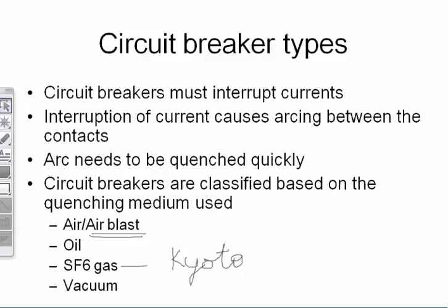It is a greenhouse gas, alright? It is a greenhouse gas, much worse than carbon dioxide. It depletes the ozone layer, much worse, alright? So you can use it. Yes, it depends on the government. Well, your options are somewhat limited for higher voltages. If you want really compact switchgear suited for higher voltages, you need to use SF6.